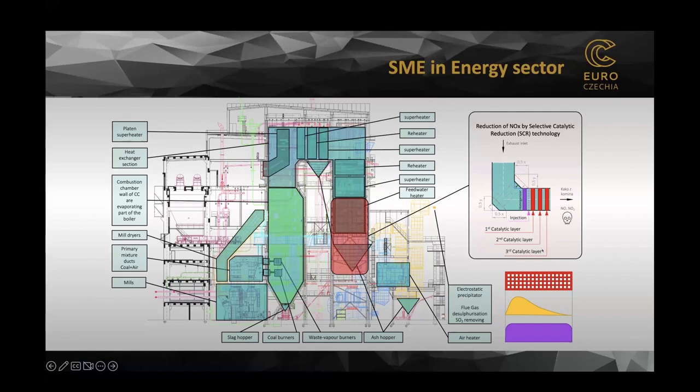There are other things too: the velocity profile of the exhaust gases should be uniform, because if it is not uniform, like on this yellow picture, it will burn out a certain portion of the catalyst, and the rest will be unused. This means that the catalyst layer must be replaced much sooner than optimal, which means it's more costly for the operator.